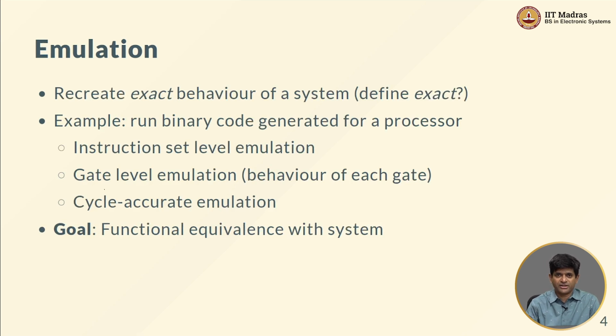This is emulation, right? And by emulation, we usually mean something a little bit more focused than what you would have in simulation. What I mean by that is, for example, we could think of recreating the exact behavior of a system. Now, of course, that term exact is problematic, right? How do I define exact? In other words, if I simulate a Verilog module right down to the gate level, I actually have a very close approximation of how the system is going to work in hardware.